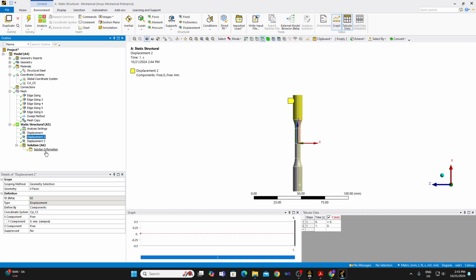On the bottom surface you are only applying the load. So you are kind of over constraining the problem, because yes, it is over constrained, and it is going to deform. It is not going to have a rigid body motion, it is going to deform because of this over constraint. So in a way you can say, it's a statically indeterminate problem. Okay, so done with boundary conditions. Now we are going to look at the analysis settings.